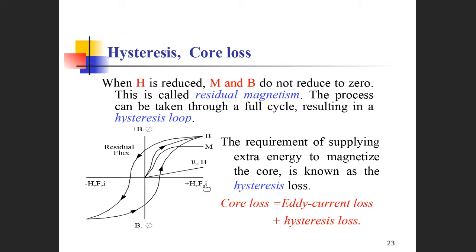Then we increase the current, or the magnetic force, or the magnetizing strength H. They are proportional to each other. Then the magnetic field increases with the increase of the current. So with H increasing, B increases. This is at the beginning, with the fresh material: you apply some current, then change the current, and the magnetic field strength increases.